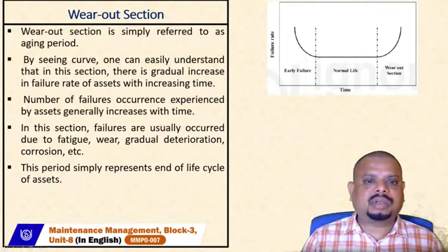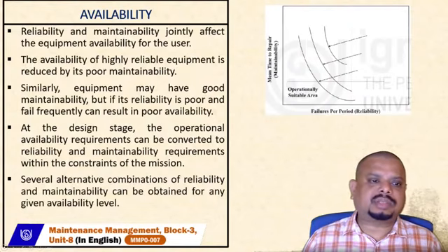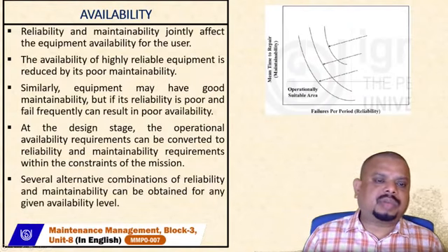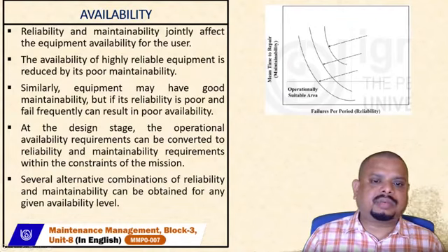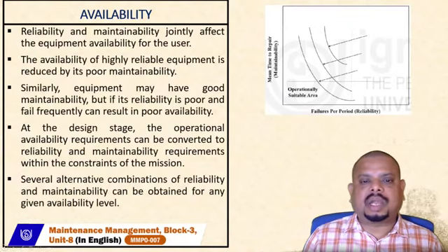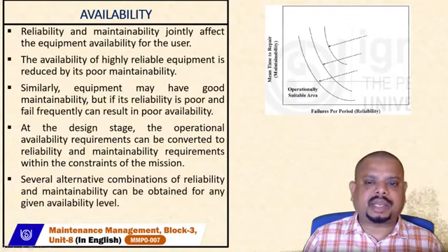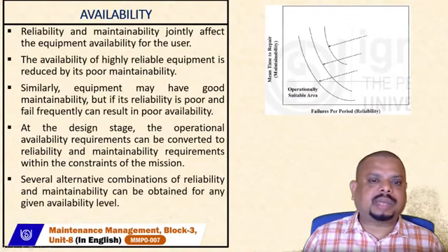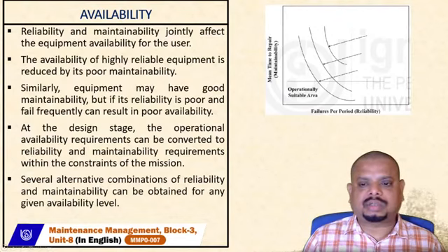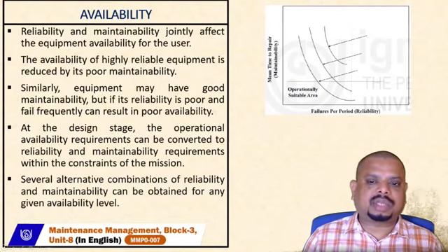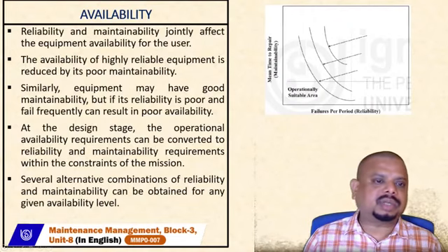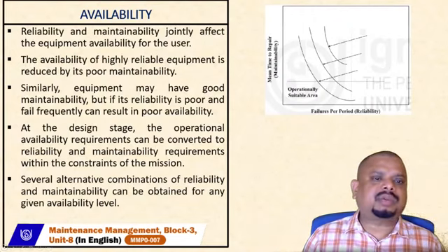So moving to the next one, the next one is known as availability. In the previous session, we understood the different aspects of reliability, the fundamental concepts of reliability, and how reliability is analyzed by Pareto analysis, that means 20-80 analysis, and lastly with the help of the bathtub curve, which has three components: early failures, average life, and wear out, that reliability should consider. So next we have to understand availability.